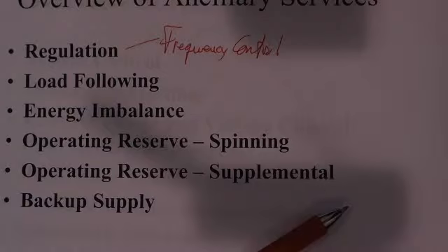There is a cost to running the valve open and close, up and down, up and down, up and down. The mechanical parts of it wear out. It does not promote efficiency. A very, very efficient generator would like to go to a certain output and just sit there fixed, and not participate in frequency regulation. So there's a cost to the generating company to do this frequency control.